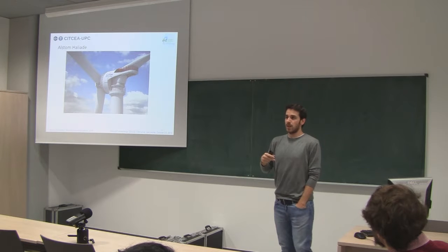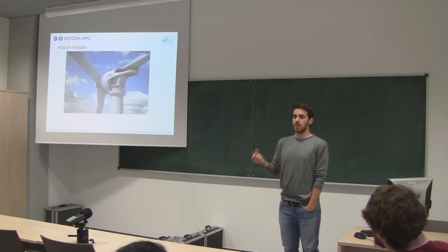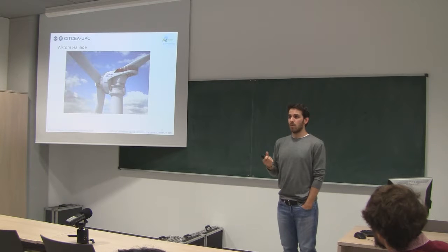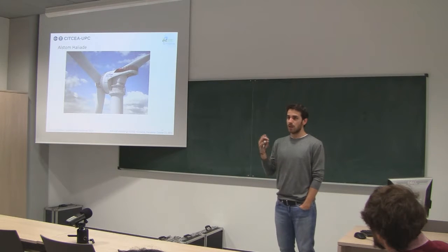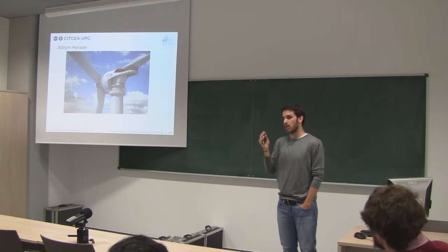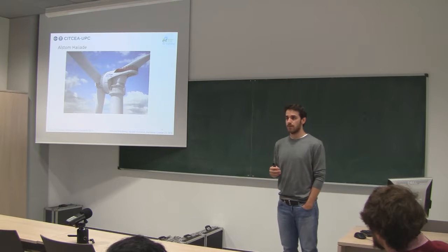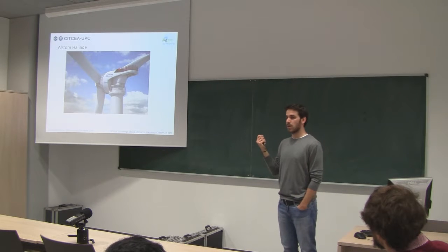They have included this generator, I think, because they want to reduce the maintenance cost. That's why it is a permanent magnet one also, and they wanted to increase the reliability and redundancy of the system, just to keep the system working even in case of certain failures. So if you lose one stator, you can still produce power with the other two. Any question about this idea?